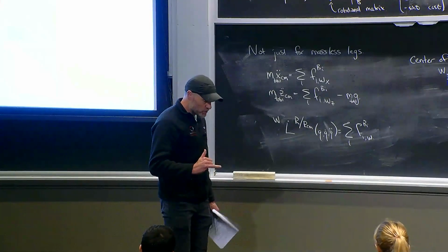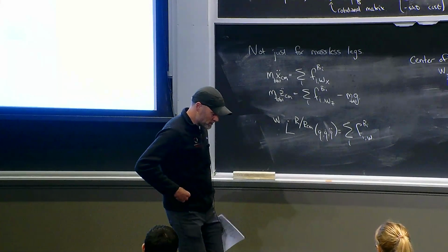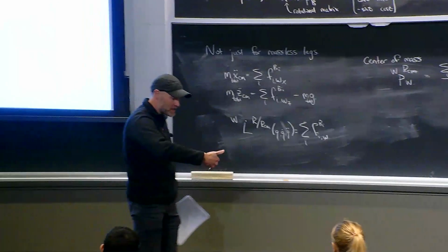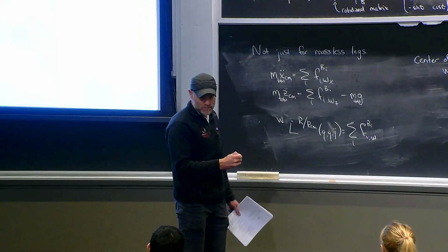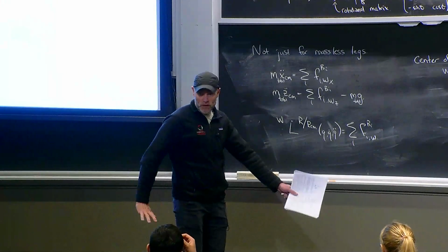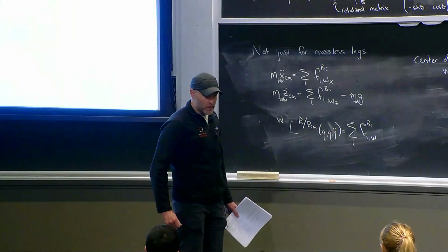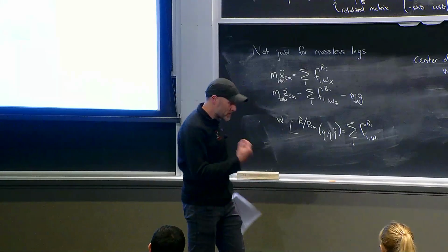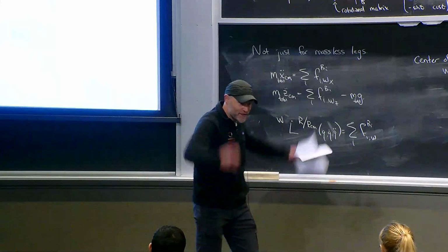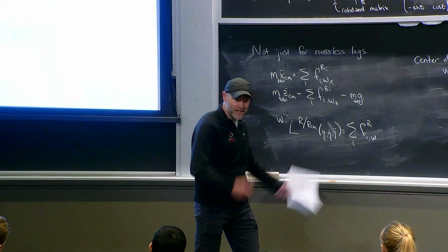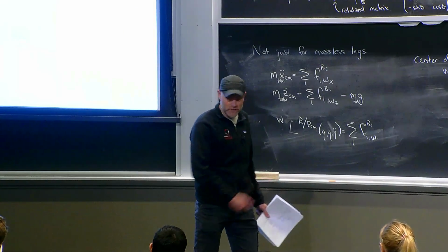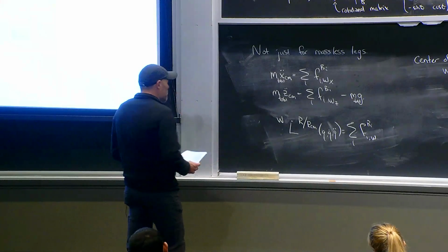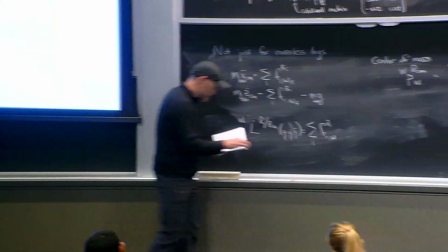What we're going to try to do is, instead of reasoning about just a point on the body, reason about the center of mass of the robot, and the total angular momentum of the robot relative to that center of mass. And that's a simple function of my ground reaction forces. Even when the robot is doing something like this to recover, nothing you can do here, unless it's creating a ground reaction force, is going to change the trajectory of your center of mass. And similarly, the total angular momentum around the center of mass. So this is the new abstraction.